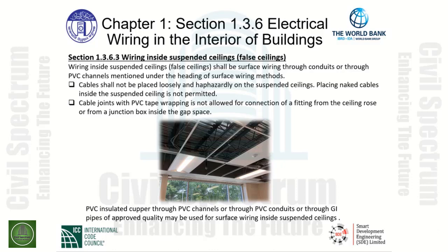buildings. Cable shall not be placed loosely or haphazardly on the suspended ceilings. Placing naked cables inside the suspended ceiling is not permitted. Cable joints with PVC tape wrapping are not allowed for connection of a fitting from the ceiling rose or from a junction box inside the gap space.